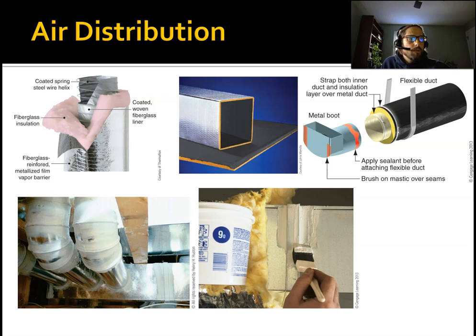There's a number of different types of ducts. Flex duct is fairly common. These are kind of nice because they have integrated insulation. They're not as good because they can end up kinked, and they have these little ridges, so the airflow is generally not as smooth. Whereas you have something like this, which is a compressed fiberglass, or you can have your metal ducts, of course.